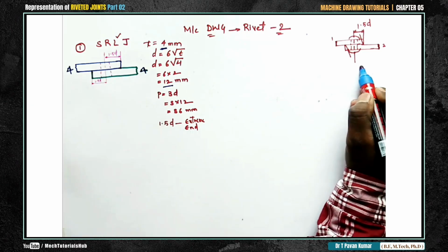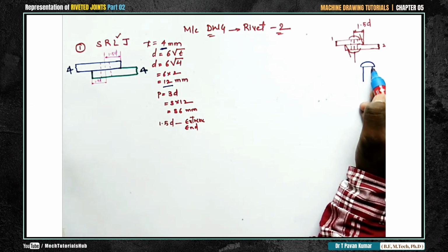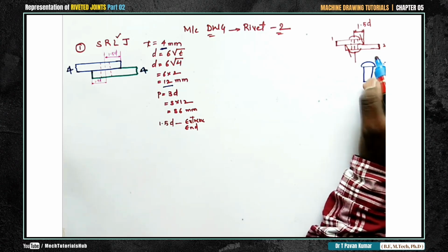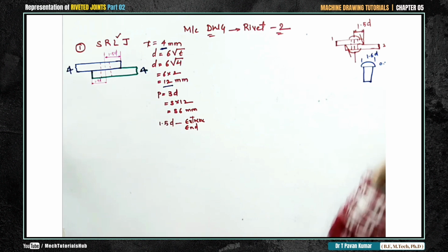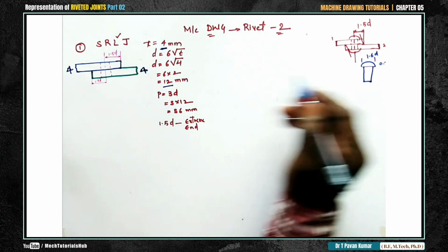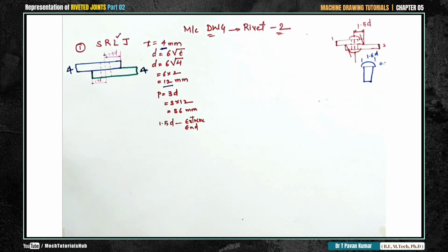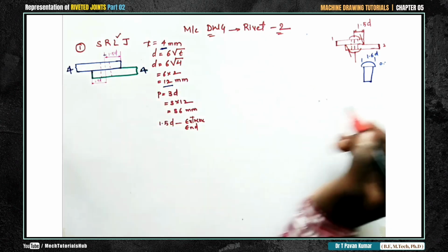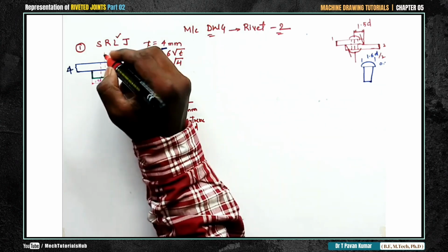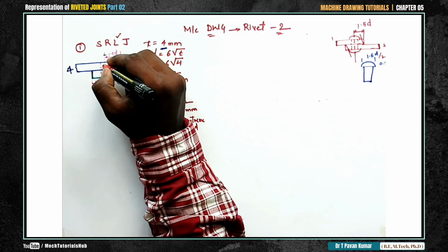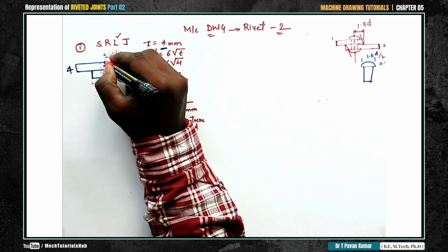Now I'll try to place a rivet of this shape. We have already seen in the earlier lecture the taper proportions, with 0.7D as the height of the head and 1.6D as the diameter of the head. I'll consider these two. How to place? I'll take 1.7D from here. I'll make a mark of 0.7D on the axis line. Then we consider 1.6D by 2, which gives the radius. From this point take a value of 1.6D by 2, which will cut the axis somewhere here, beyond the intersection.